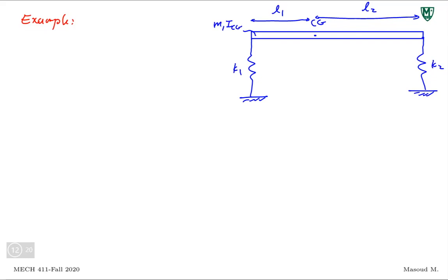You have a bar going up and down and rotating. Right? You have something like this, oscillating like this, most probably. So it's not just that it goes up and down. This is 1 degree of freedom. The second degree of freedom would be the rotation it has. It oscillates like this. So this is a system with 2 degrees of freedom.